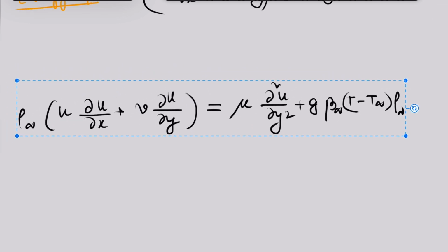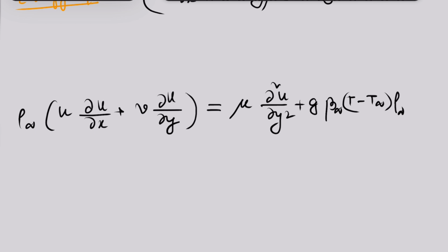So this should actually be your mentality: if you are given any kind of problem, be it fluid mechanics, heat transfer, or solid mechanics, try to obtain the governing equation first by simplifying the most general form of the governing equations you have. In fluid mechanics, or rather for continuum mechanics, the Cauchy-Navier equation is the most general equation.